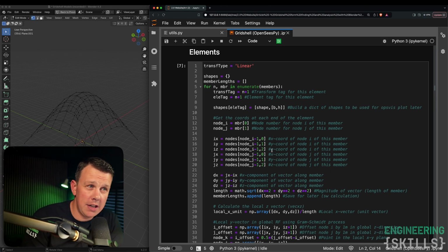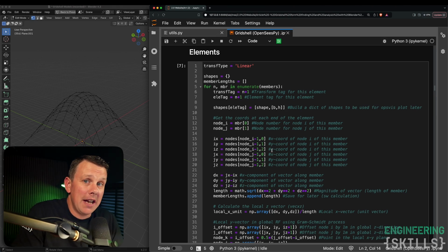So what we have to do essentially is, for each element, construct an orthogonal XYZ reference frame local to that element, and within that reference frame one of the axes is going to be the z-axis for the element, and we're going to use that to specify the transformation for that element. This is really the only complication. This is the additional headache that comes with doing a 3D model versus a 2D model, right? Once you've understood this, everything else is easy after that.